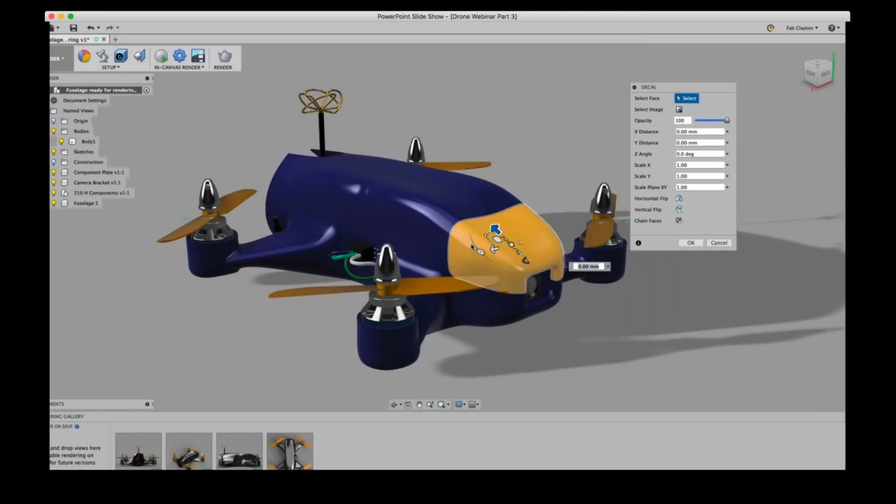And then once it's in, you can adjust the image. Like in my case, I need to rotate this a little bit, to 90 degrees. I mean, you can enter a degree there on the Z angle. I just did it by hand, but you could enter a specific angle if that's needed. And then you use the edit form, right? You change the scale here. You just click on it, change the position.